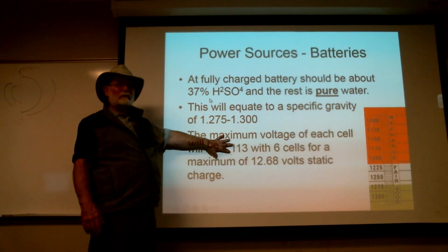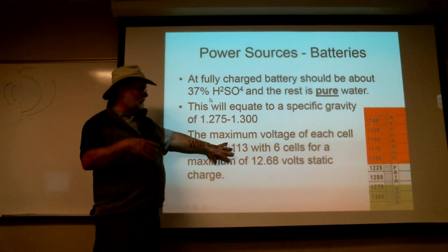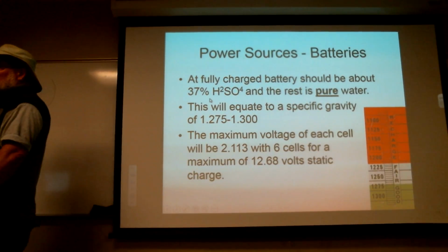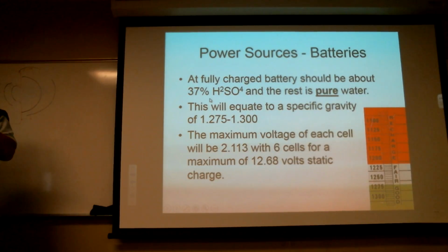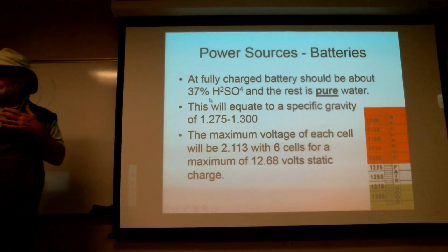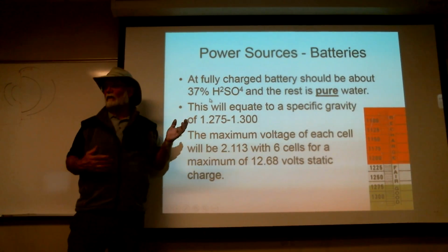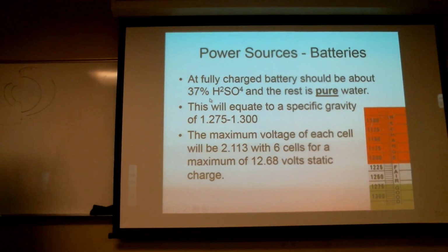With the AGMs and some of the newer batteries, which they'll talk about next week, you actually want to be about 14.2, 14.5. You also don't want to mix technology. If I have that 14.5 volt charging system and I put a regular lead acid in there, it isn't going to last very long. It's going to overheat it.